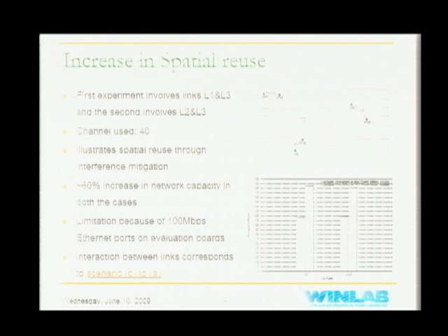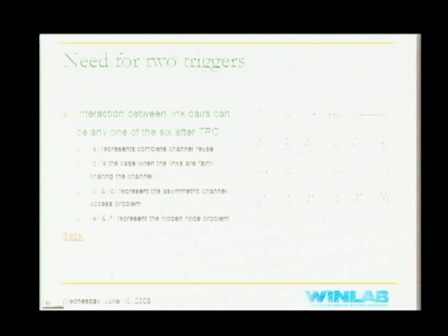When link 1 and link 3 operate at maximum transmit power, they basically share the channel. This experiment shows the transition from scenario B to scenario A. If they are in scenario B and you use transmit power control, they will go to scenario A where they achieve perfect spatial reuse. That's what we want to show in this experiment.